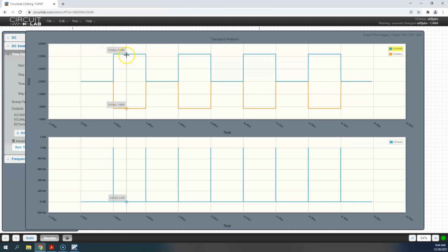What that means is I've got to wait until it's finished. If it's got a valid message that it's putting on the bus, whatever the device is, that message has to finish before somebody else can use the bus. Once it's done, there'll be a period where the bus is quiet, and then that very important message can be put onto the CAN bus. So they may have to wait a few microseconds, a few millionths of a second, until the bus is free.